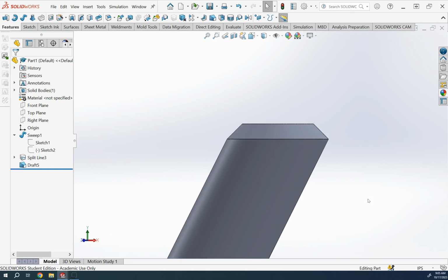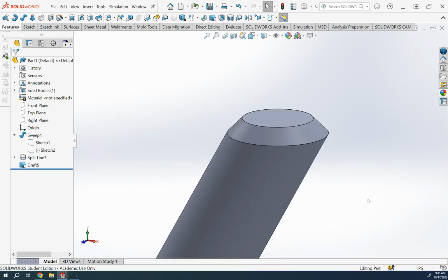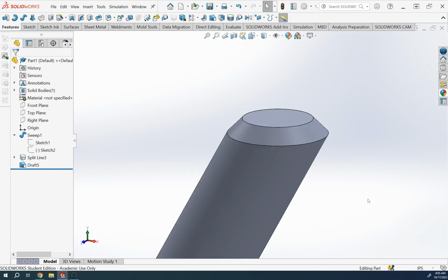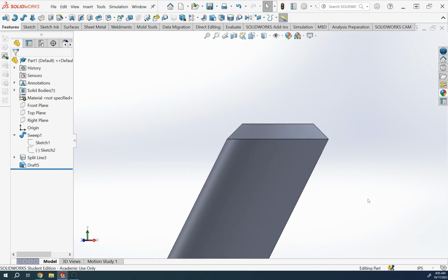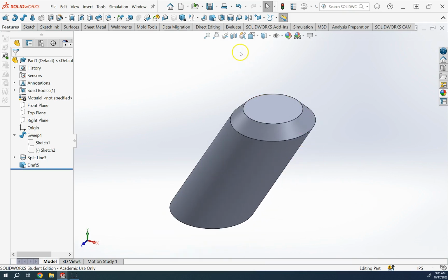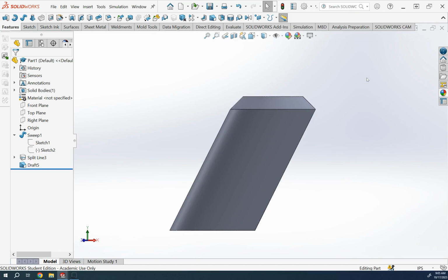Look here, 45 degrees with respect to the surface, and clearly a uniform 0.3 in all directions. So you can get that chamfer. You see I used the technique with the split line for a chamfer that was not possible.